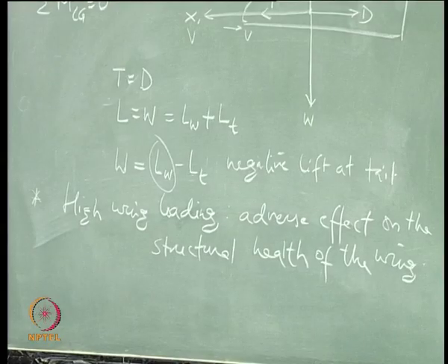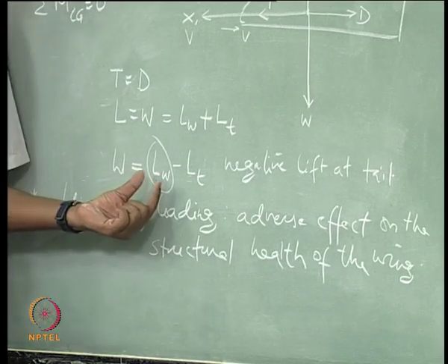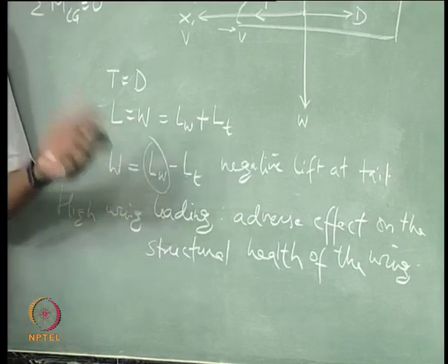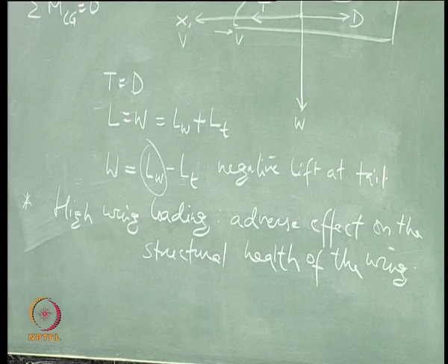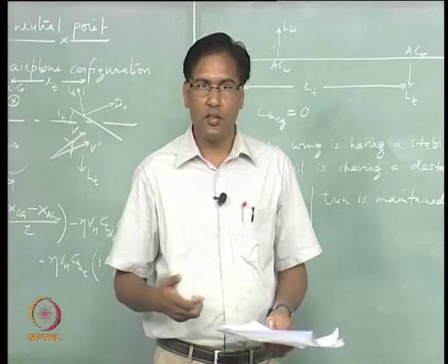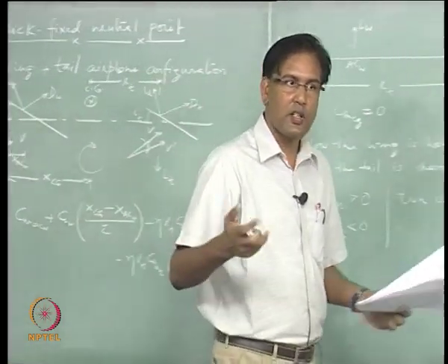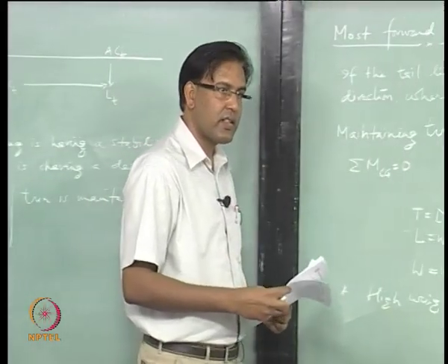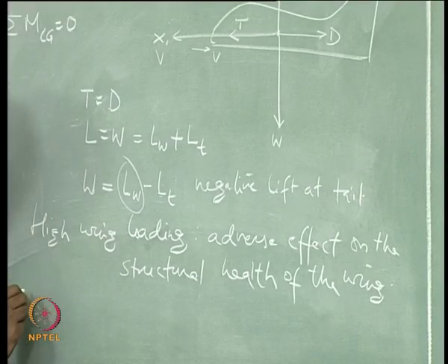Performance of the aircraft will also suffer, right, because if this lift has to go high, your angle of attack has to be high, and that is going to create more drag, right. More lift is also giving you more drag. So, definitely it is going to have an effect.